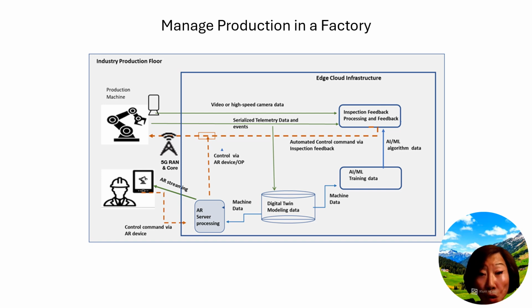A process control function can compare machine data, for example, position, rotation level, speed, sensor data, high-speed photography, and high-resolution video from the manufacturing line, issuing commands for corrective measures if necessary. These process control functions reside on the edge infrastructure, with corrective inputs sent back to the production system control function.